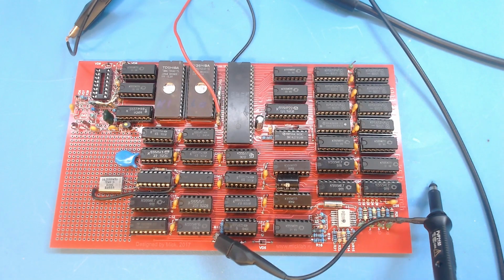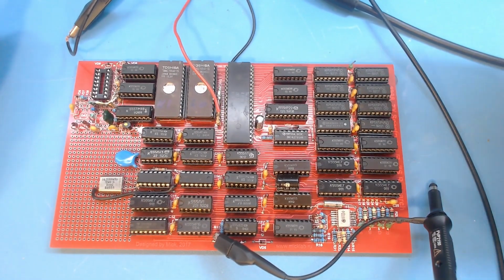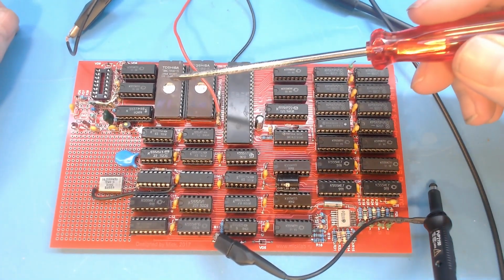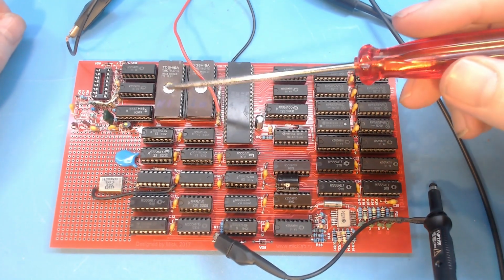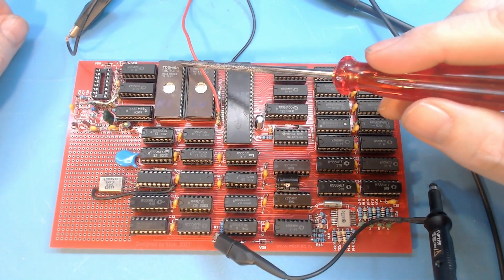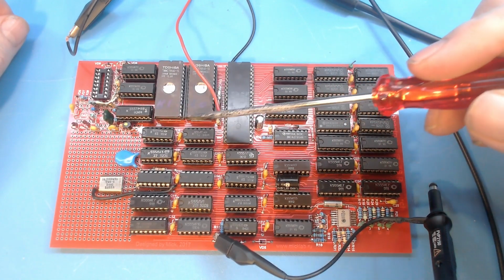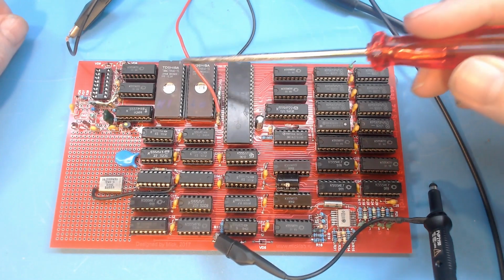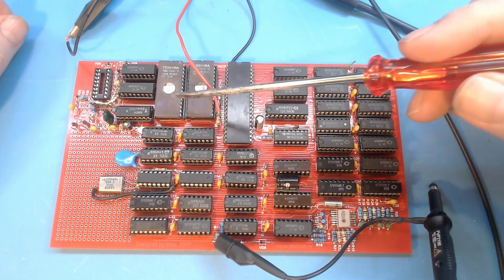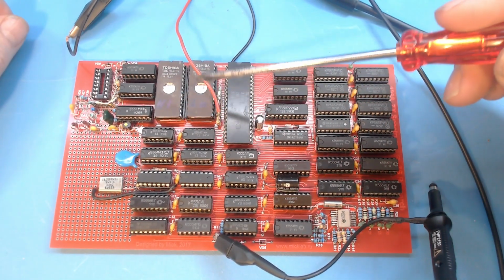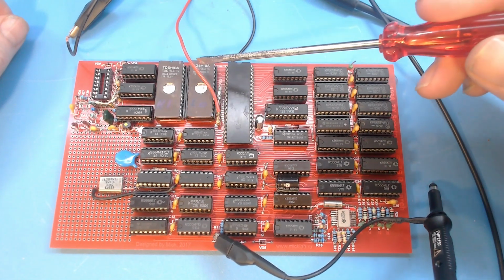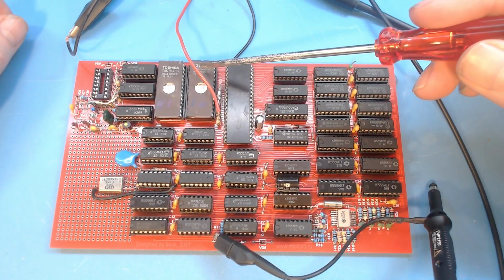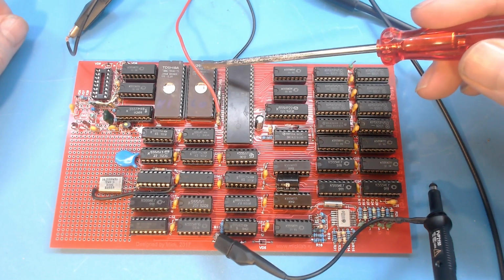And this is the board as it is now with the redesigned circuit. As you can see, I've replaced the EPROMs or EEPROMs with the ZX Spectrum diagnostic ROM as made by Phil Ruston, the 1.45 version, and I split it into two files and burnt it into two 64K EEPROM chips.